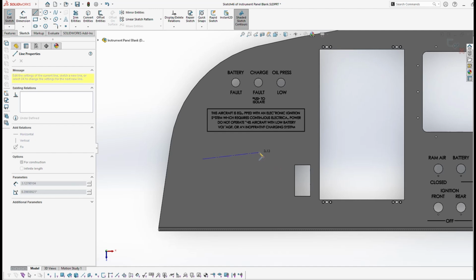You'll notice the way that the SolidWorks sketch tool has some kind of snap features, if you'll call them that. That's to make a horizontal line. I can make a vertical line. I can make a line that comes to the end of something that already exists, or the midpoint. Or if I come down here, it would be the center of the circle, or even tangent to the circle. Pretty powerful features. But in this case, I'm just going to click a line. I'm actually going to make this too short on purpose. Come back and explain why in a little bit.